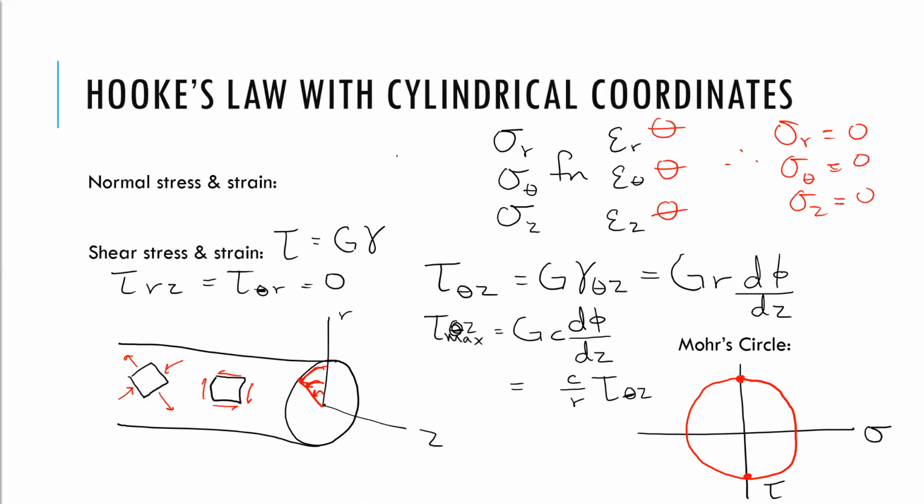So this brings up kind of what is positive, what is negative. Remember that if your shear stress is pointing in the positive direction on a positive face, that's positive. So your Z positive is in this direction. The way that I've drawn that there, it's easy to get yourself confused. Don't fall into the trap I almost fell into. R is coming up out of this. Right, R would be coming out of that element. So which way is theta going? Is theta going up to the top or down to the bottom?